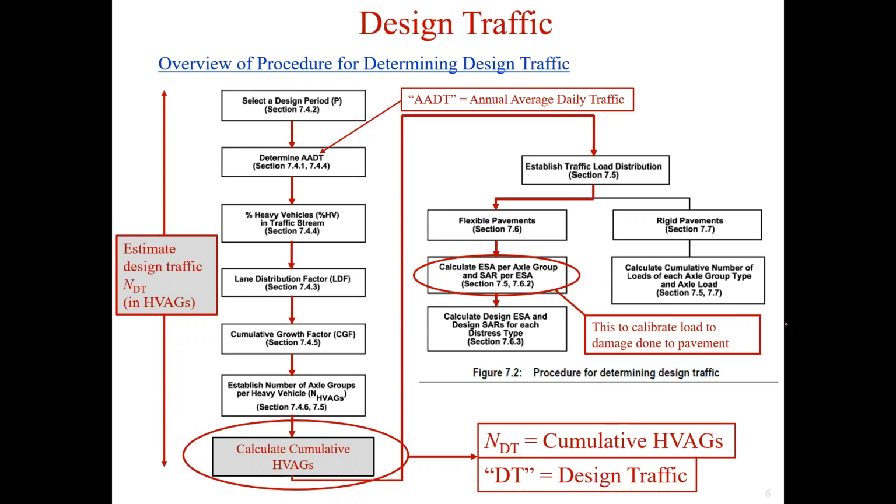The pavement design task is to select a suitable pavement configuration for the traffic portion of a carriageway. The traffic way may vary from a single lane catering for traffic traveling in both directions to 6 or more lanes for single direction traffic. For multiple lane carriageways, the same pavement configuration is usually adopted for all lanes.